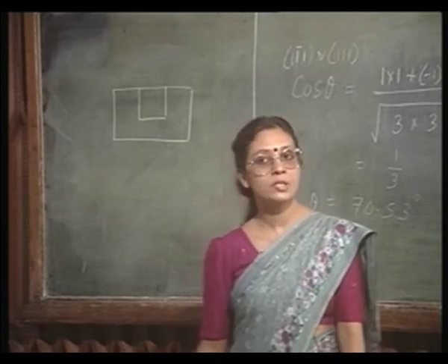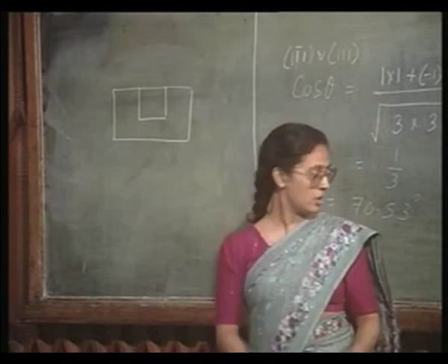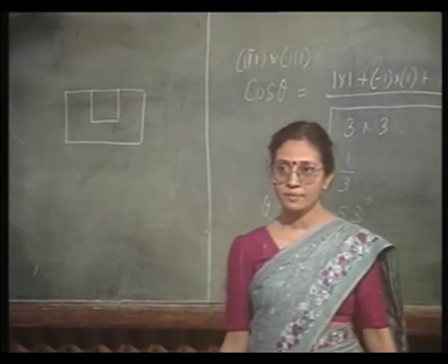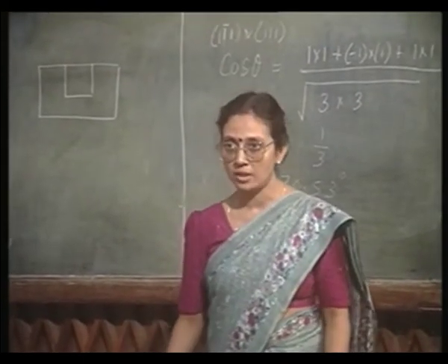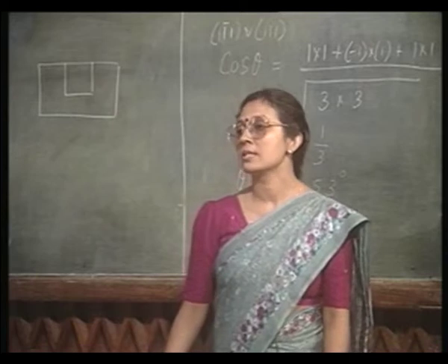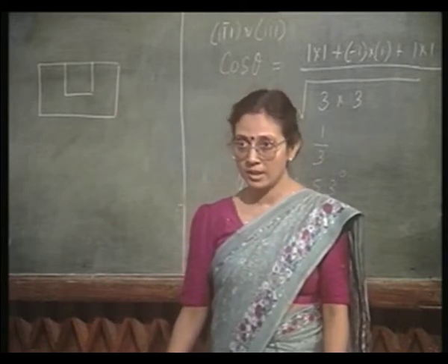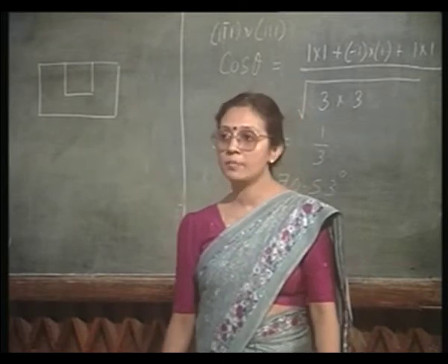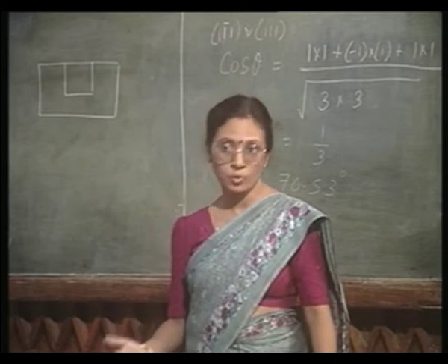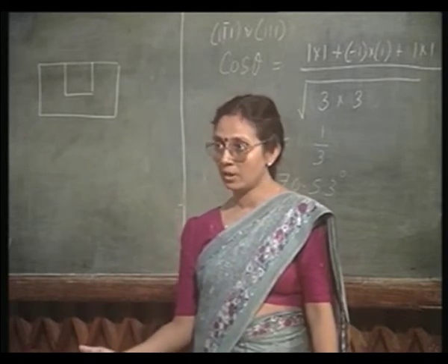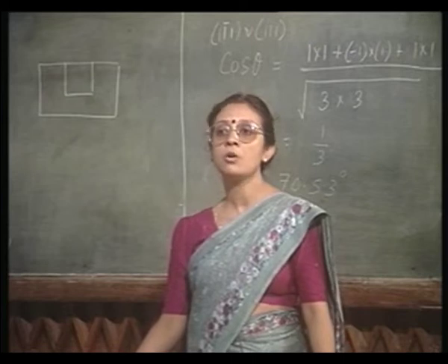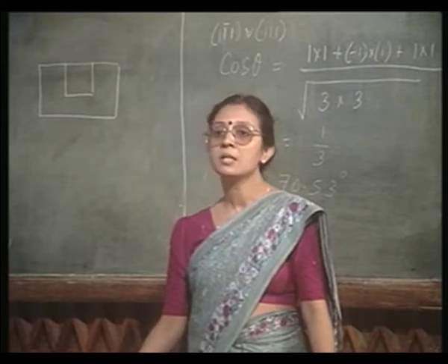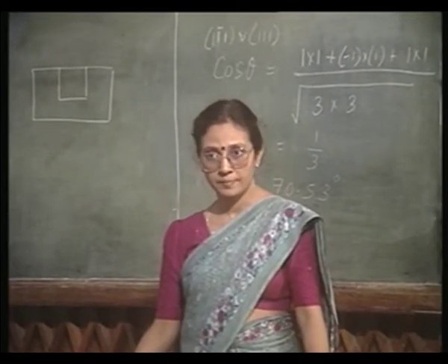right. So, what have we seen so far? We have seen that since 111 has the least spacing between two planes, it is easier to grow the crystal along that direction. Also, because it has the highest tensile strength, it is the natural cleavage plane for silicon, and we have seen the angle between the 111 plane thus exposed and the surface plane, whatever the surface plane may be, 100 or 110 or 111, and you have seen how the scribing is going to be done.